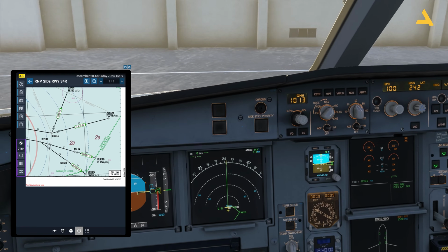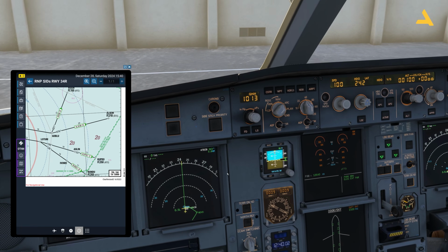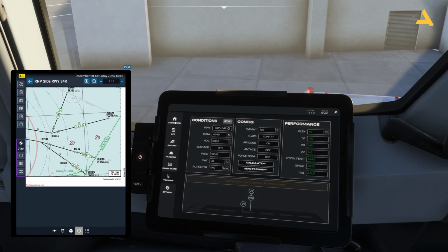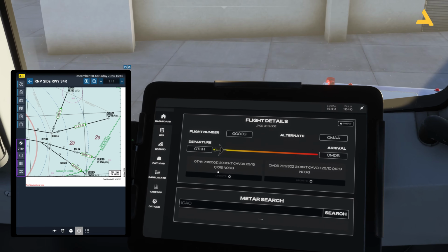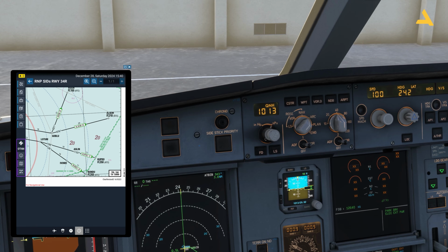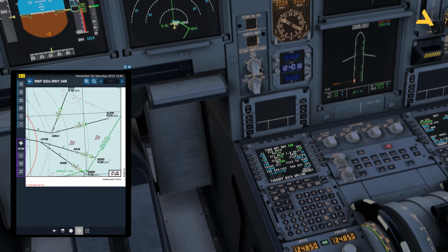It's actually the standard altitude, or the barometric pressure is 1013. So above this altitude, you will move to the standard one. But right now, as you are below this altitude, that's why you have to adjust the altimeter as per the weather that is given to you right now. This is 1019. So you have to enter 1019 over here. So after 13,000 feet, you have to change it to standard. And you just have to bring your cursor over here and press it and it goes to the standard atmospheric pressure, which is 1013.